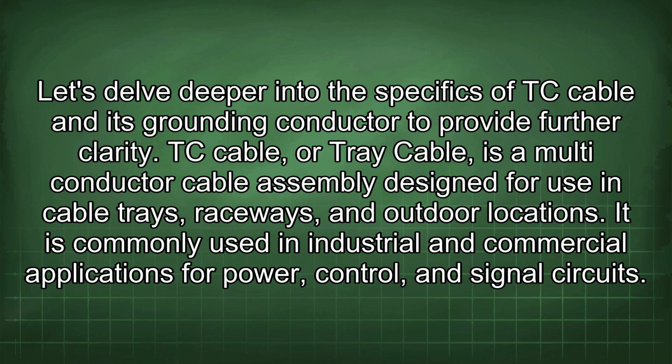Let's delve deeper into the specifics of TC cable and its grounding conductor to provide further clarity. TC cable, or tray cable, is a multi-conductor cable assembly designed for use in cable trays, raceways, and outdoor locations. It is commonly used in industrial and commercial applications for power, control, and signal circuits.